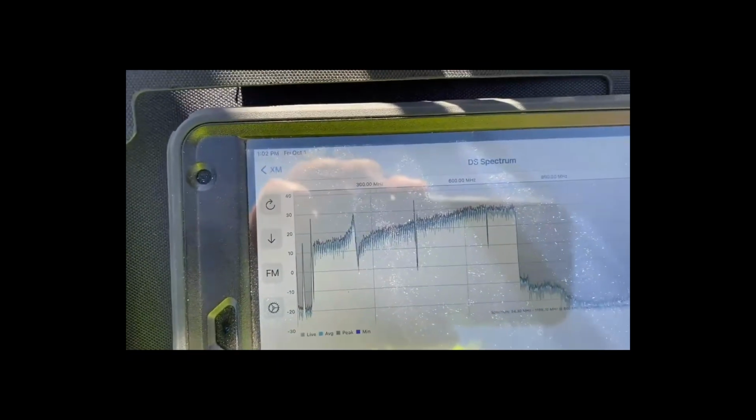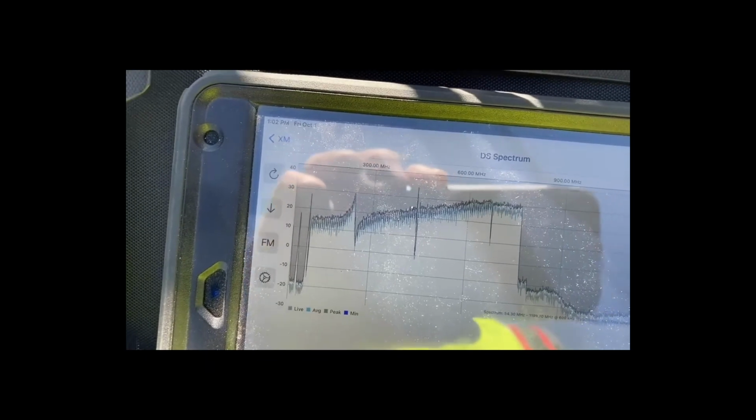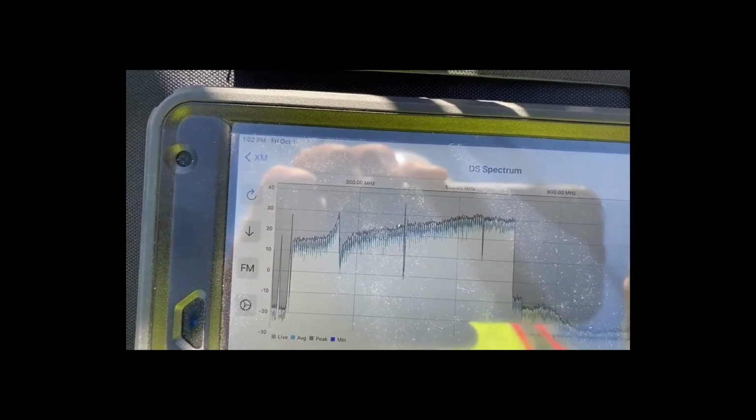Bigger than life. Okay, well, we're gonna put in another tech signal interruption and try and reseat this module and see what happens. Okay, so we took the module out of the housing, checked it for corrosion, checked for signs of damage or water migration inside the housing. Everything appeared to be in pretty good order. So we went ahead and reseated the module.